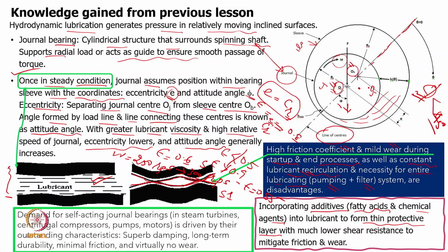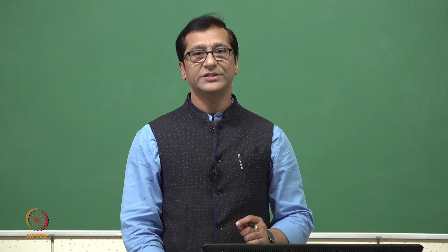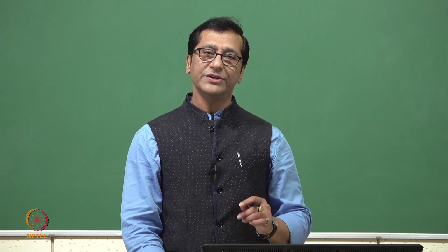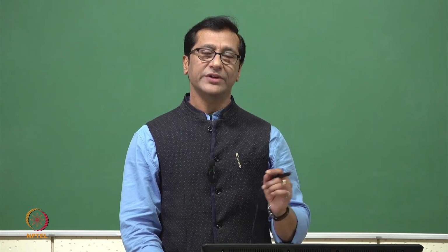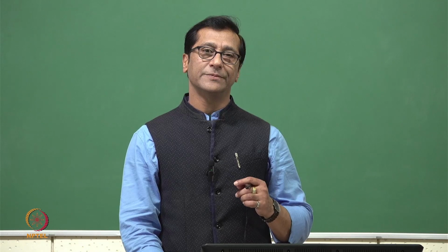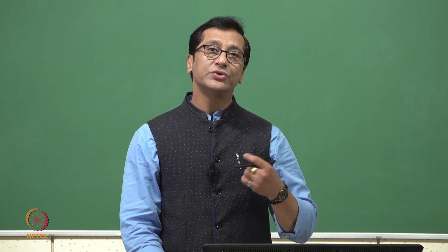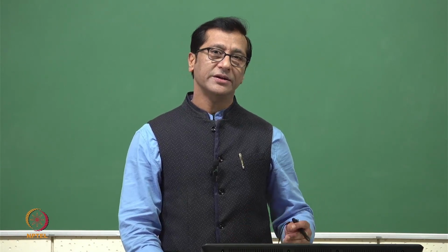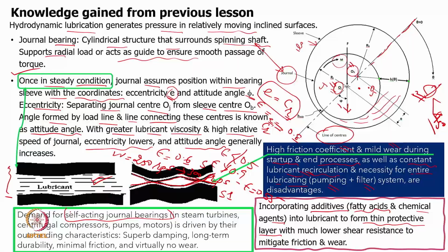Now, why are we talking about hydrodynamic bearings or the hydrodynamic lubrication mechanism? One major point is that it is self-acting. What is the meaning of self-acting? If the load increases, the journal position changes on its own. If speed increases, the journal position changes on its own. So it is very effective. We are not really regulating the journal position, or not controlling it completely, even though we know that we can go ahead with active control. Here the control happens on its own. That's why the name self-acting journal bearing has been used.